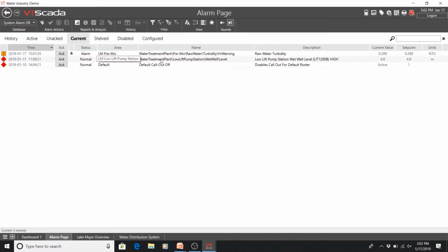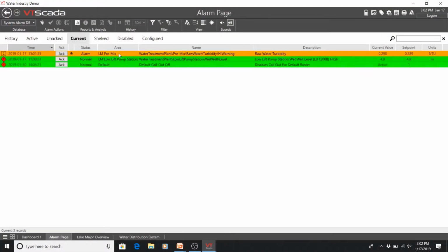There's some more stuff there. We're going to move on past that for this purpose here. And that is, I want to take this turbidity warning. That one's been going off a whole bunch. Anybody not in the water industry? Anybody? Okay, so the turbidity is basically the cleanliness of the water. Does that make sense? So what will happen is you've got your clear water there. It's sending some sort of a light signal based upon the reflectivity, based upon particles. It gives you a turbidity unit. NTU it's called. That's just the idea behind it. So it's looking at how clean the water is.